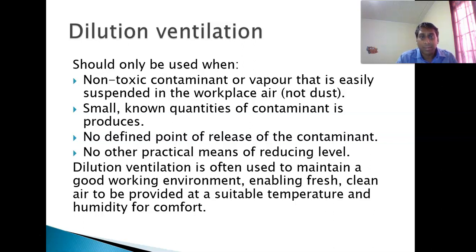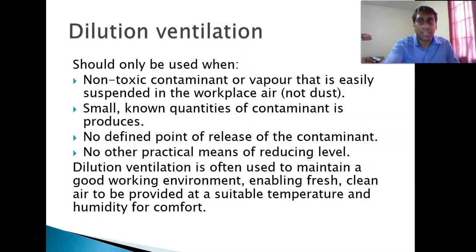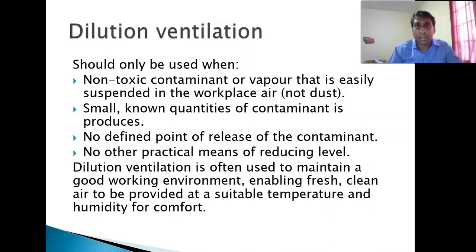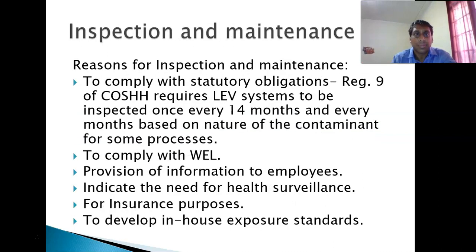Inspection and maintenance, I'll just talk you through this one. You would have remembered in the very first slide, which would be on the other video, that we mentioned this is in compliance with the COSHH regulations. The Control of Substances Hazardous to Health Regulation 9 requires that the LEV system be inspected at least once in every 14 months, and every month based on the nature of the contaminant for some processes.